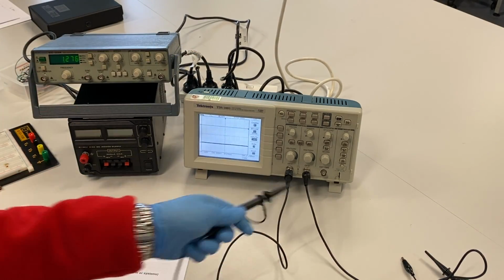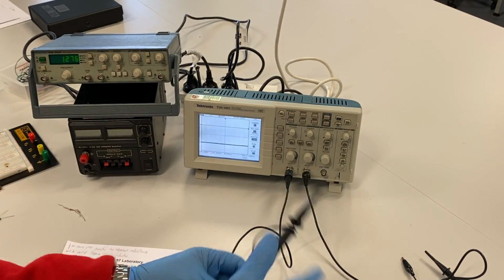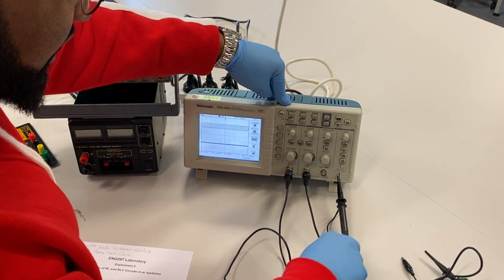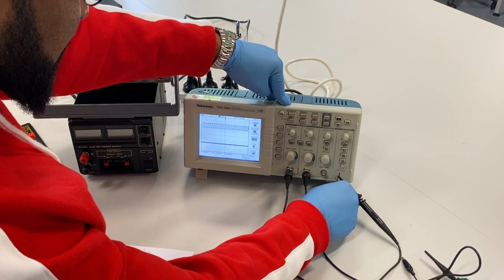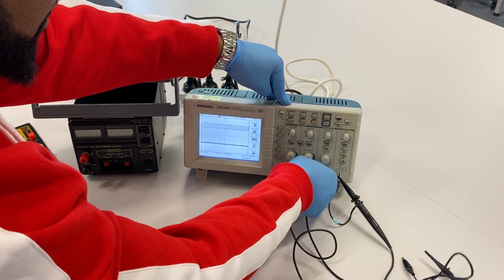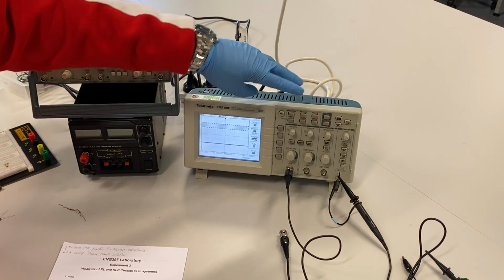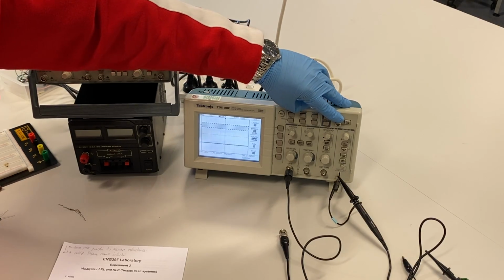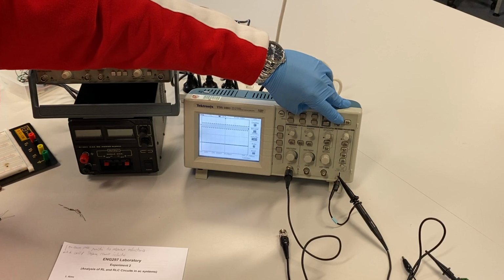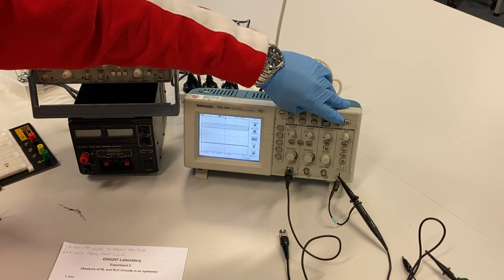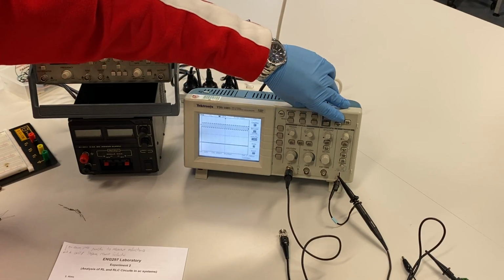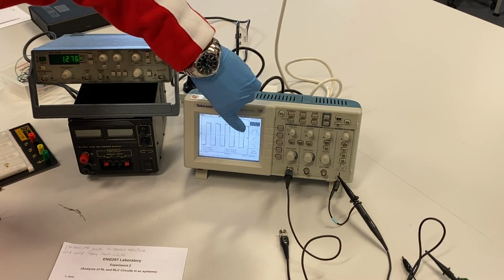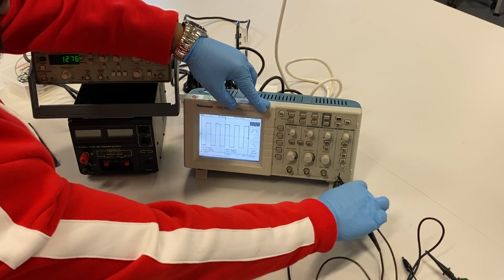There's a connection on this side of the oscilloscope. If you can see, there's this knob on this side. The top one is the positive side. Then you connect the ground one to the ground. This is channel 1 that I'm testing, so let me just remove this so that you don't get confused. What I do is press auto set. Auto set works more like the run button that you press for a simulation to run. So you just press auto set. If you get a square wave, it means this cable is working. So we just remove it and put it aside.